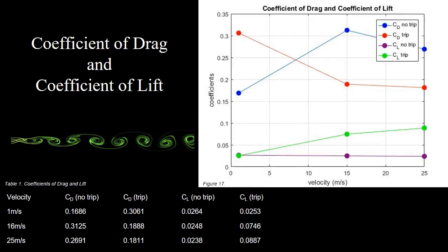Using an approximation of the cylinder as a polygonal prism with 24 sides, the same number as the ports, and assuming that the ports are in the center of each of the sides, pressure drag and lift coefficients have been approximated for the cylinder in all of the cases tested.